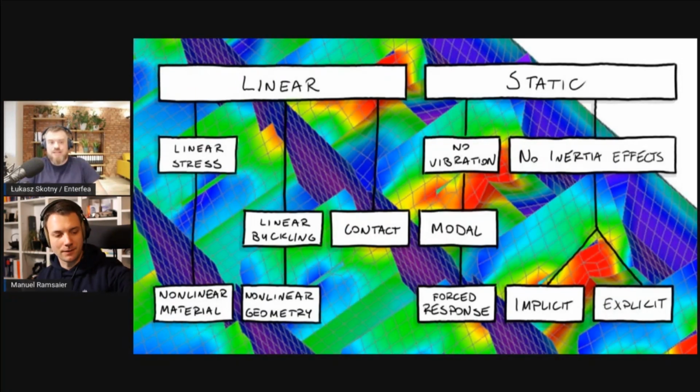Like how the sails in a ship work. You have the horizontal beam on the top, horizontal at the bottom, and there is a cloth. When the wind blows on it, if you would calculate this cloth as a beam, the bending capacity of it is non-existent. It's nothing, and yet somehow it didn't break. That's the nonlinear effect because of the geometry.